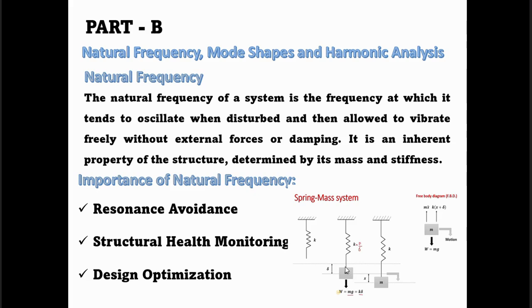It is referred to as static deflection. Next, after giving some initial displacement x to this mass m, the displacement of this mass is now x. After giving this initial displacement, without applying any external load, this body will start oscillating. Oscillating in the sense that this line is the mean position of the mass, and it is going to oscillate to and fro along this axis.